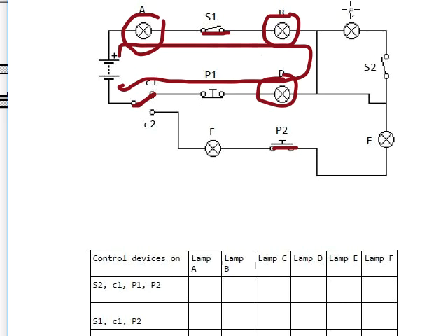For example, this one is going to be off because this side is open. This one is off because even if taking this path it looks like it's connected, both to the positive and the negative as well, the other terminal of the lamp is not connected, because even if we are closing this push button here, the circuit is open. So I guess the answer is A, B, and C, but we can check it with this